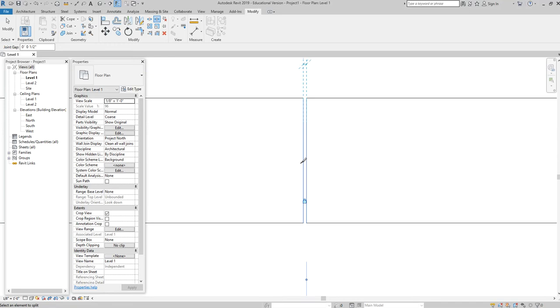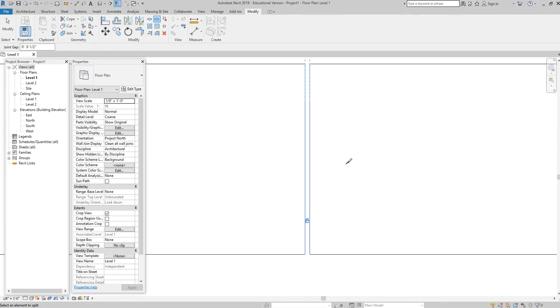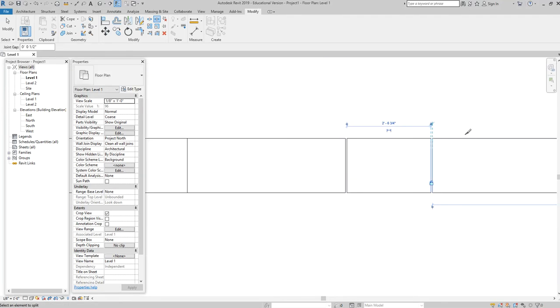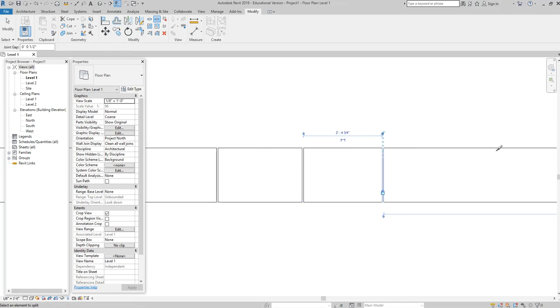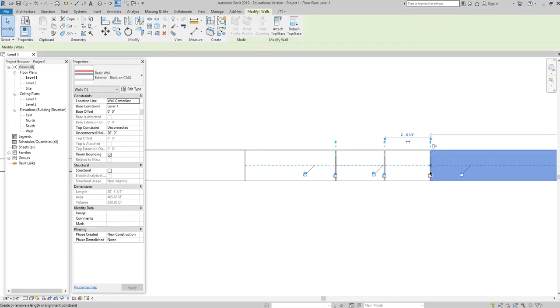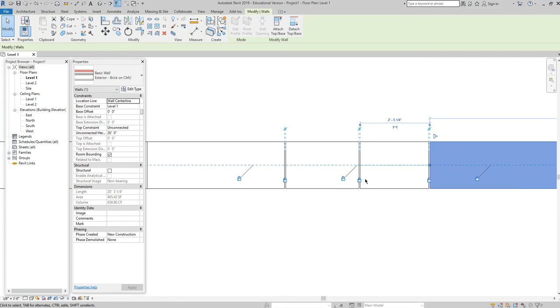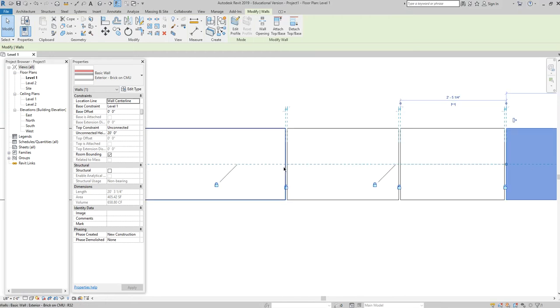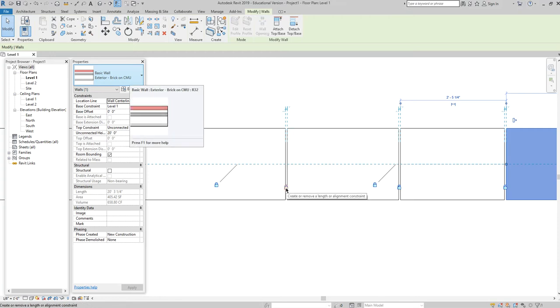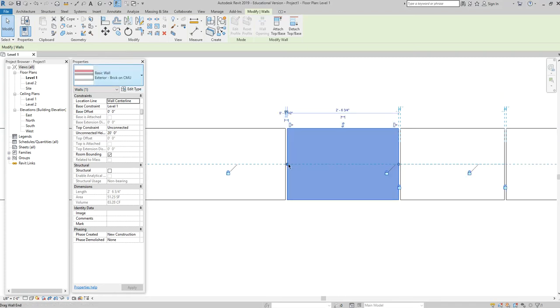Click, and it just creates a 1/2 inch gap right there. Click, and I can make these sequential, click, right? But essentially I'm just creating these little gaps, and you're going to notice that I get all these little locks happening. If there's a little lock here, that means that it split that gap with a 1/2 inch gap, and that Revit is locking that dimension. I can undo it by clicking on it, right? But essentially that is our split with a gap.